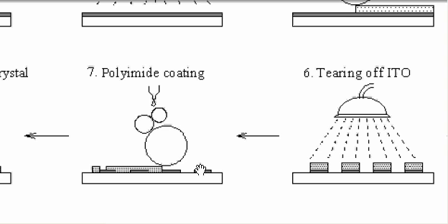So why use a polyimide? Because the liquid crystal needs to have alignment to have the same orientation. So we need some polymer material to orient the liquid crystal molecules. And polyimide is the most stable material there.